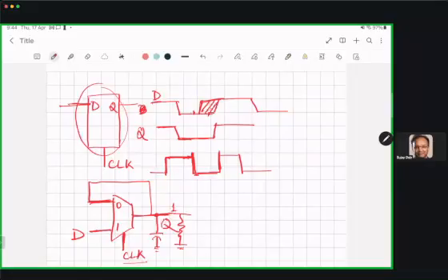It might happen that my clock period is quite high, so I want this value to remain high till the next positive level of the clock comes. To achieve that, I have to introduce something here so that this capacitor remains charged. So what can I introduce here?